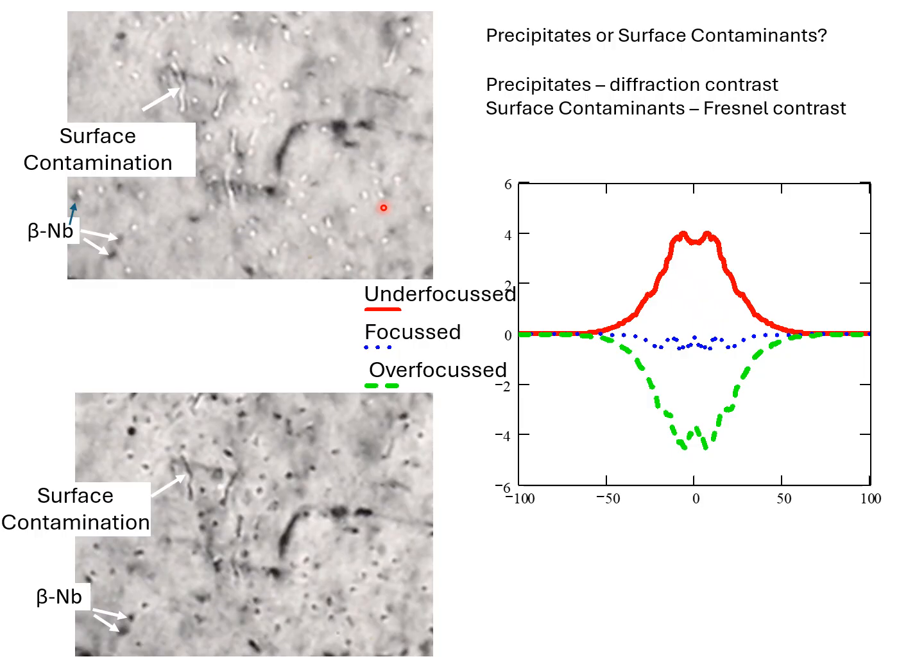Zirconium alloys don't have cavities, or very rarely, especially Zirc 2.5 niobium, because zirconium doesn't produce helium, and we don't have the conditions, certainly in reactor operation, to create cavities during irradiation. But when you polish the sample, you often leave residue on the surface, contamination. In this case, it's kind of an amorphous niobium-rich oxide. And this shows up with Fresnel contrast. So this is a surface deposit.